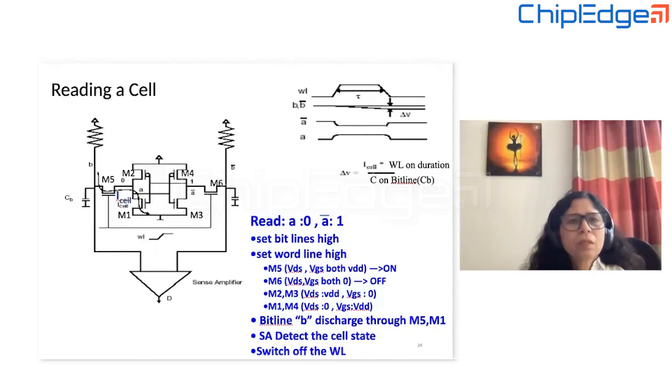How is write margin related to time, because it is a unit we measure in picoseconds or maybe microseconds? Write margin, normally we say, is about how much the bit line needs to be taken near to zero. If I'm doing a 1 volt operation, can I take it down up to, let's say, 300 millivolts, 200 millivolts, 100 millivolts, and still I can write? Then I would say I have a write margin of 100 millivolts, right?